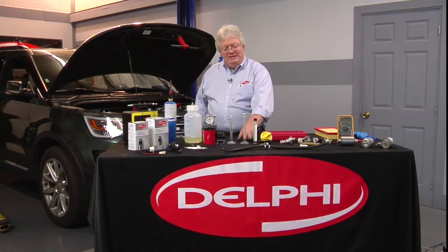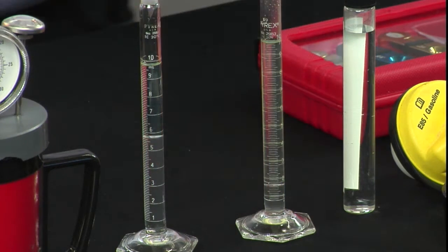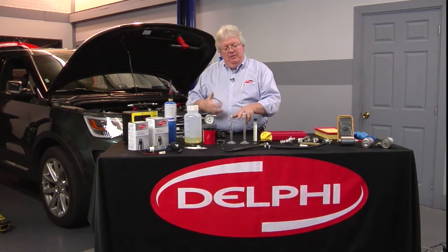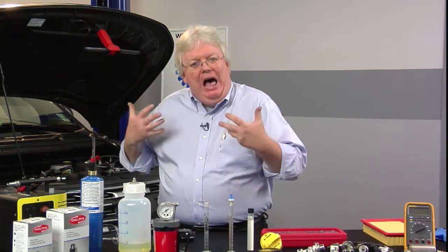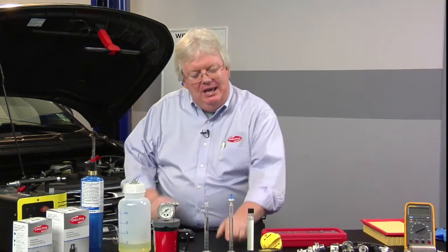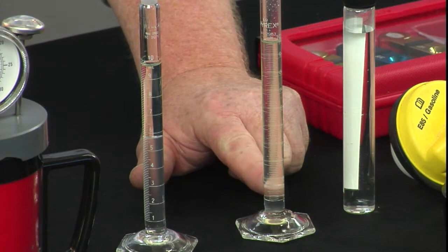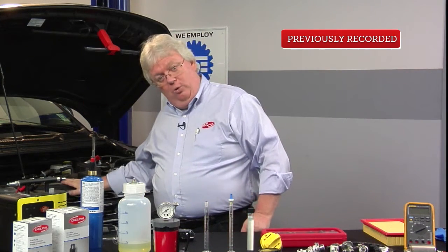So as we let it settle, we see this one over here on your right is at 1, actually it's a little above that because it's E10. E10 is normal pump gas. So that will mix some of that water into the overall sample, because water is suspended in alcohol and the alcohol mixes with the gas. So I've raised from 1 ml, which is the water I put in here, up to almost 2, about 1.7. So we have about E7, about 7% alcohol in the gasoline, quite acceptable for this Ford that's not flex fuel.